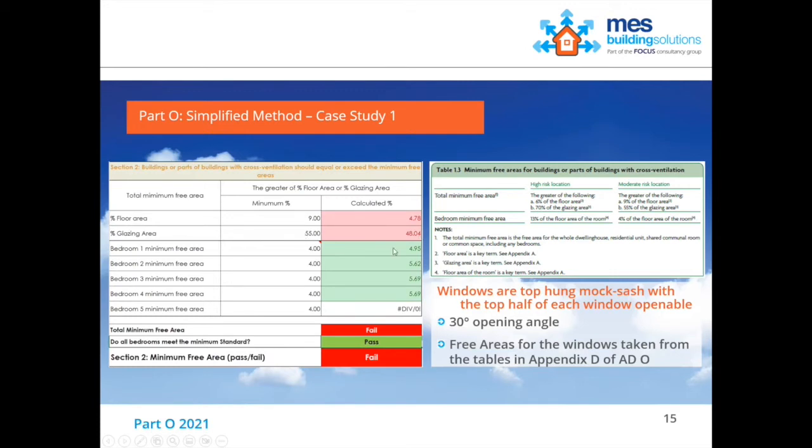So for this particular orientation building, the windows don't open sufficiently to give us enough free area to get that heat out of the building. We've got small enough area of glass that we're not going to get too much solar gain, but that solar gain at the moment can't be got out of the building when it's slightly cooler overnight.